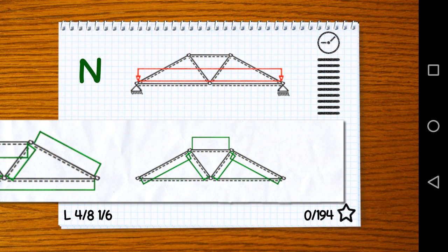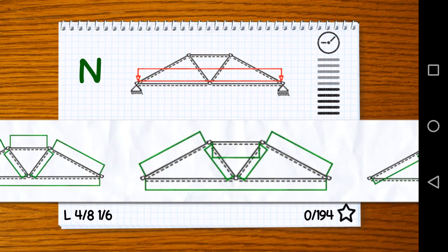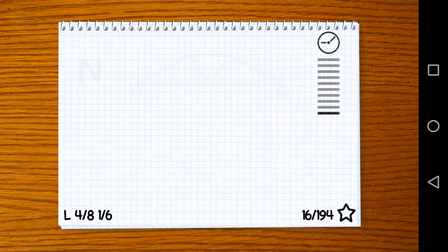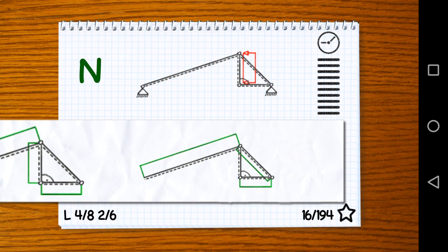Okay, here we have like a truss, and the trick here is to consider the whole truss like a beam, and the whole beam here under a distributed load would lead to tensile stresses on the lower part. So the lower horizontal elements are under tension, the upper elements are under compression. And then what happens in the middle is normally we can just compute it, but here this is the right answer. The other one had some wrong values basically.